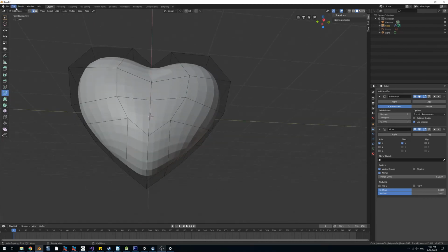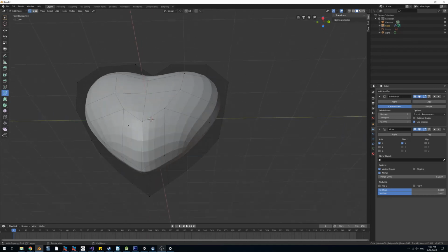I'm going to go into my edit mode, I'm going to select vertices, and I'm going to choose knife. And when I do that, I'm going to click on this vertex here. And you see how it turns bright green, which means I've selected the vertex. And I come up here and you'll see that it actually locks onto this vertex. I'm going to click it and then press return. And what that does is it accepts that cut point.